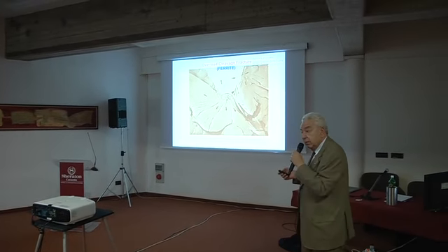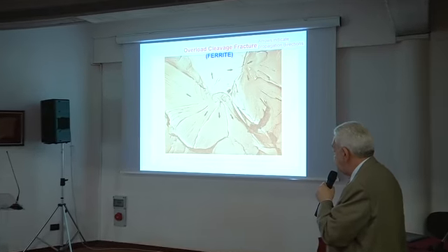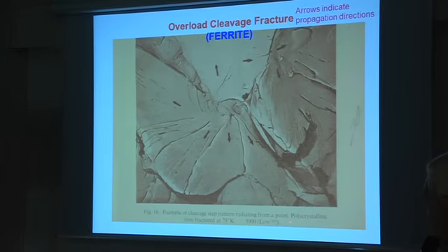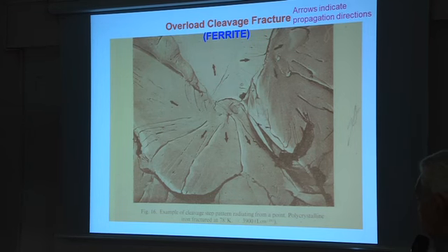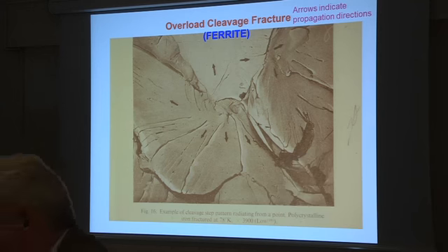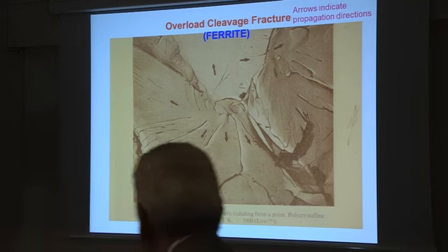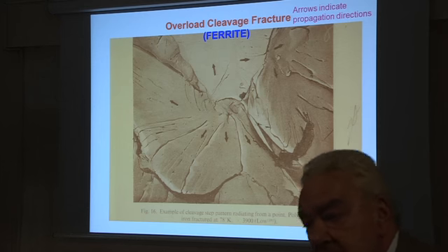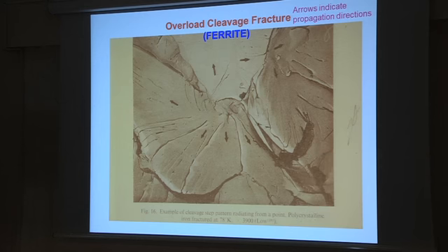This is ferrite, pure ferrite, which is, as you can see, very low carbon because it is polycrystalline iron fractured at a very low temperature, 78 K. So we are for sure in the brittle mode. And we have a little carbide from where the stress built up, and then the fracture propagated in all the different